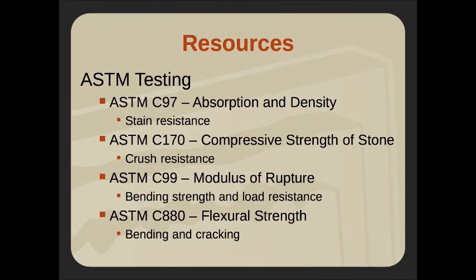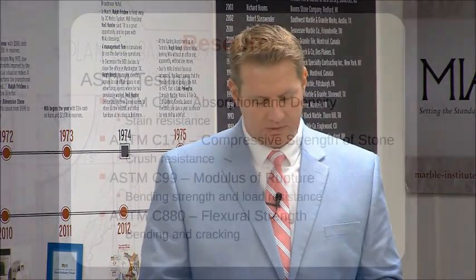So if it's just pedestrian traffic, it's generally not going to be much of a concern. Our typical thicknesses are probably going to be just fine. But if we get out into vehicular areas where we're going to have lots of vehicles, fire trucks, garbage trucks, what have you, we need to make sure we understand what the compressive strength is and that we've designed the thickness of that material and the setting mechanism and setting method in a suitable way so that we know that crush resistance is going to be there for us.